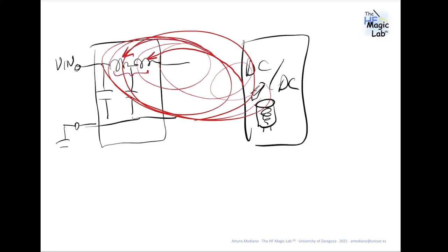So if we put them in different layers, that means that between them you will have a ground layer that is sealed in. It's like when you are doing the layout of a PCB and you want to avoid crosstalk between traces. You have an aggressive signal and a sensitive signal. One of the strategies is to route the aggressive signal in layer number 1 and the sensitive signal in layer number 4, for example.